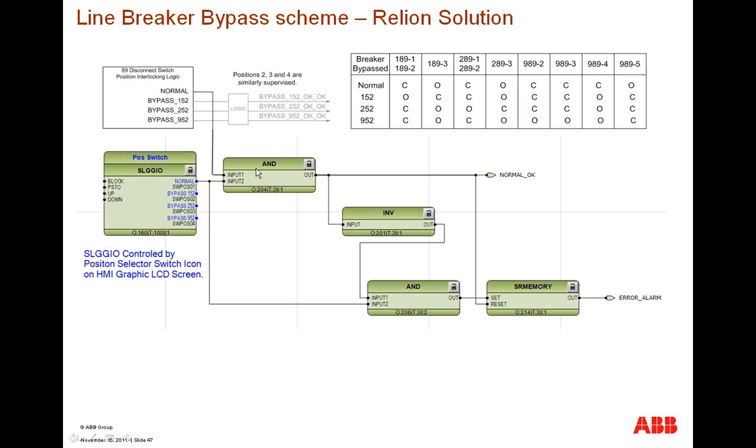If we are not in this particular configuration, if the switches and the actual system configuration do not agree, we can go to some error. Here is shown the logic developed for the error alarm. If this error alarm goes off, this can then drive either DNP remote indication, or ring bells, or light up lights at the station.